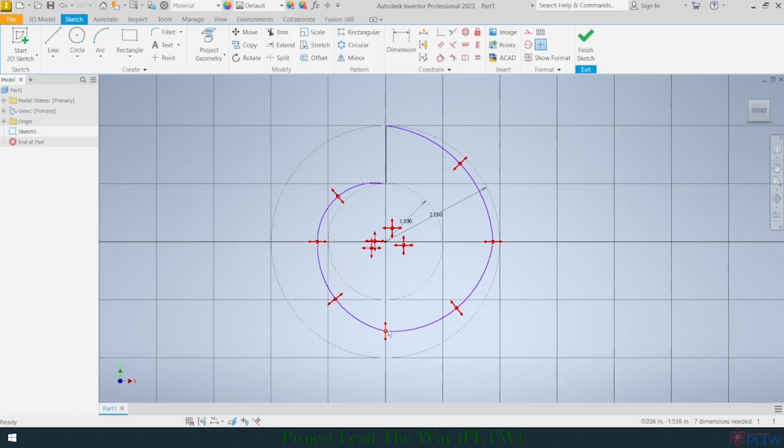That's what I want. This endpoint of these two arcs here can move up and down, but cannot move left and right. And the same as this one right here, it can move left and right, but it cannot move up and down. We're not really too concerned about these other ones, but that's pretty much what I want. And so I'm going to turn the degrees of freedom back off.